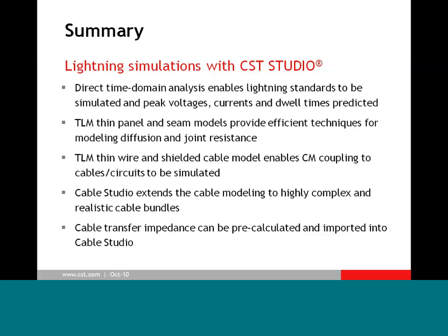I think we have some nice features such as the thin panel model, the C models that allow you to efficiently capture some of the physics that's very important, the panel diffusion, joint resistance. The thin wire model and shielded cable model allows you to investigate common mode coupling to cable and circuits, particularly looking at loop areas and magnetic field coupling to loop areas inside the system.